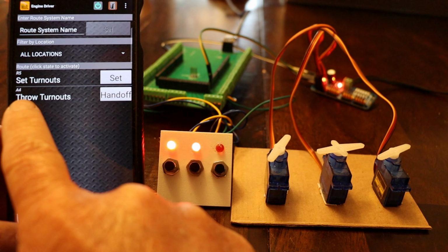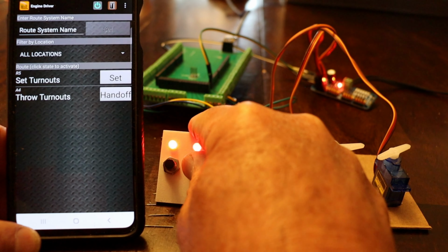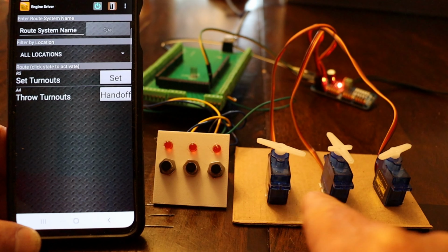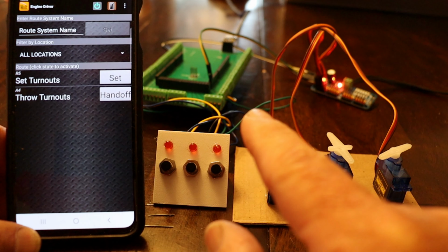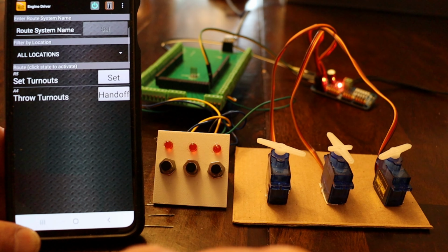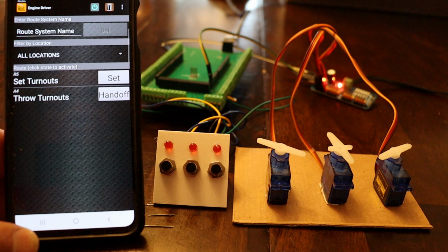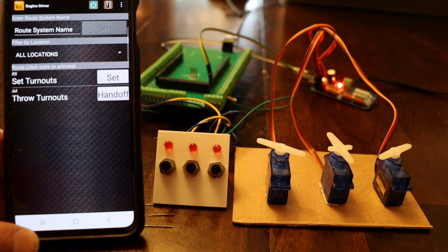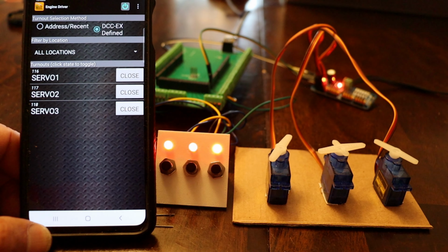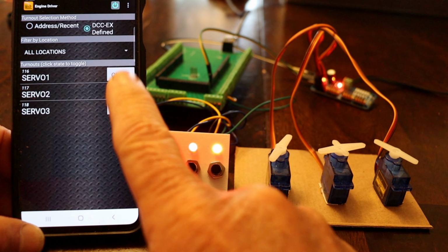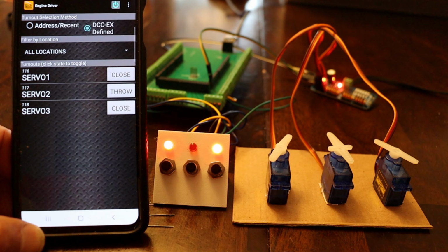Okay. Now, the other thing we talked about was the automation, and I was writing that little script that every 5 seconds was going to change the position of the servo, of a turnout. Now, I didn't auto start it because I wanted to be able to go through this and show you what's going on, but now that I'm ready, we're going to start this, and every 5 seconds it's going to start changing the servos. There we go. There's the first one. And as it's doing that, we'll come back to the turnout screen, and you can see these will update as it goes through its routine. The LEDs update, the screen updates to show what's happening. So everything communicates with each other and does what it's supposed to do.